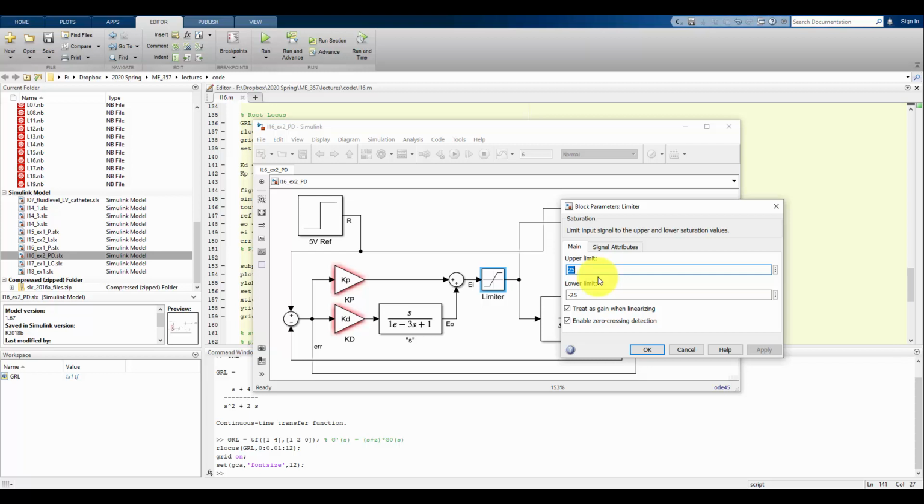Now, this is good because it really gets the controller started in correcting the error and bringing it to 0, which is to say bringing the reference and the output equal. But it might be very high and not really even achievable depending on what the actuator into the system is, or like in this, let's say it's an electronic system, it might require an extremely or even infinitely high initial voltage as the input. Well, practically speaking, we can't do that. We can't provide it this infinite input.